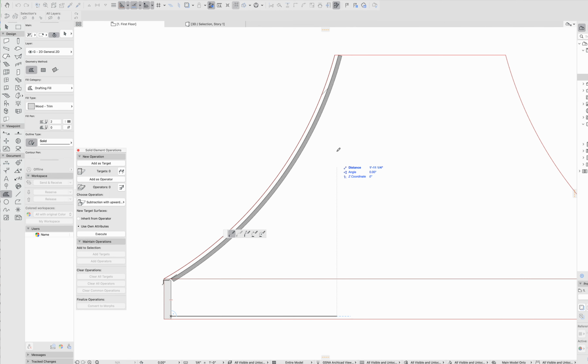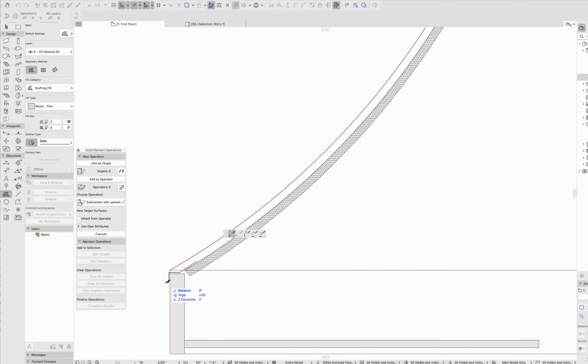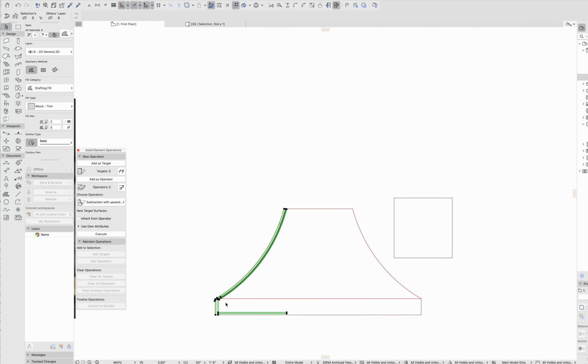If, for example, we know that this is the depth of our overhang, I could even show a soffit in here. You could show, like here, I have the flashing. You do want to be wary of your level of detail. I know that complex profile beams can report errors if you have too small of dimensions, so some of this stuff you have to be a little bit cautious with. But in this case, I've drafted out essentially what this eave detail is going to look like.